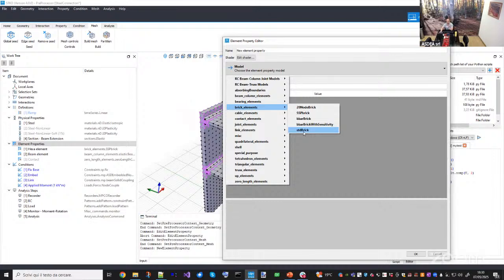So since the plastic part is incompressible, you have to choose an element that does not suffer from volumetric locking. These kinds of elements are either the complete reduced integration brick element, which is the SSP brick, or the B-bar brick. The B-bar brick is a special formulation that is similar to the SSP brick in a way, but it only reduces the integration of the volumetric part of the deformation.